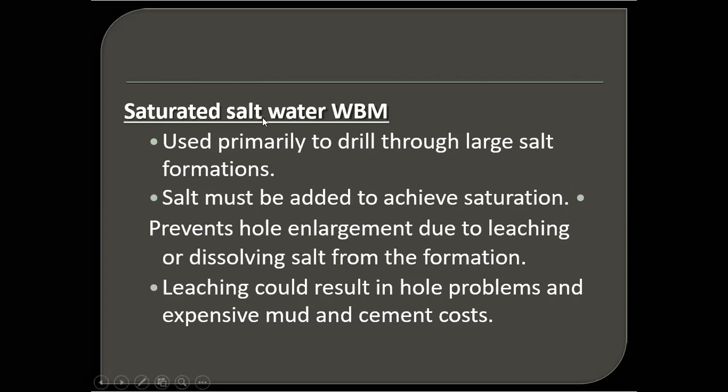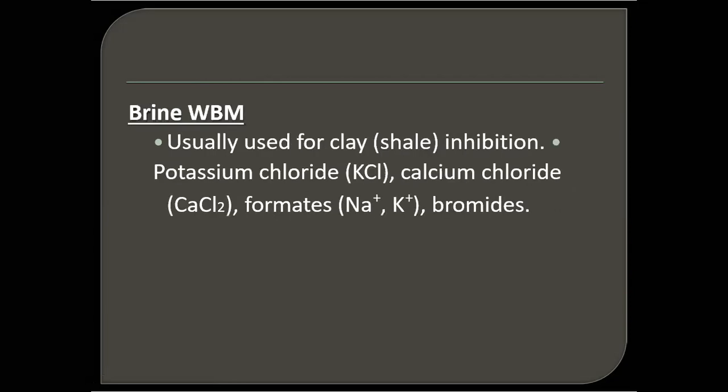With saturated salt water, when you encounter a salt formation, you can use it because it will be compatible with that formation. It will be almost the same, so it should be fine to work there. And it is usually used for clay inhibition. Then we use KCl, calcium chloride, formates, and so on, the brine water. But this is the least used.